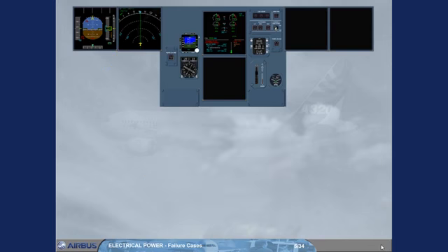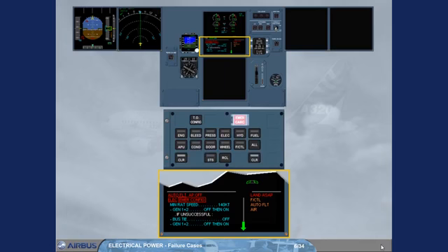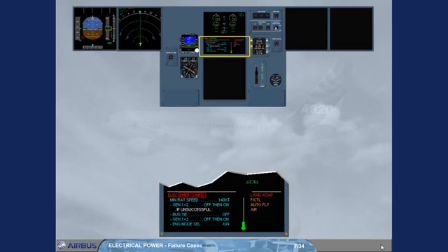On the engine warning display, you can read that the autopilot has disengaged. Let's deal with this first. To continue the procedure, we will clear this line by pressing on the clear key. Read the title of the failure. The red emergency configuration title means that you are in an electrical emergency configuration. The red message, Land ASAP, orders to land as soon as possible.